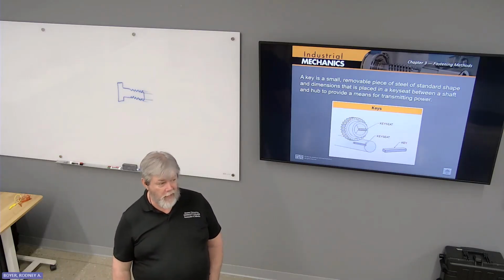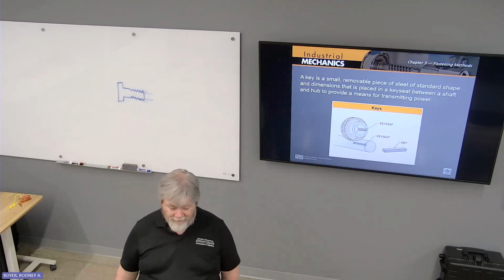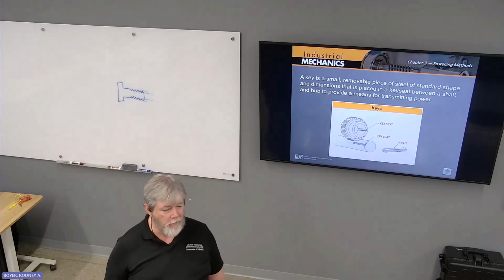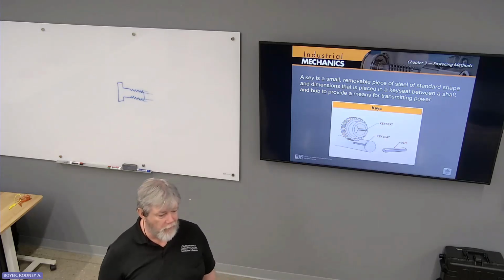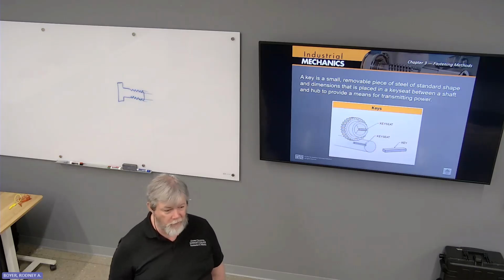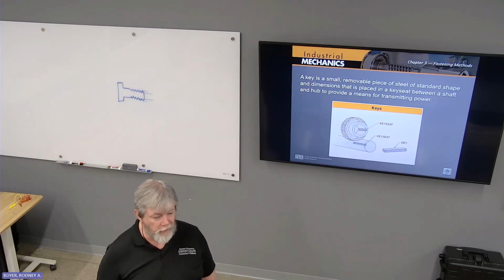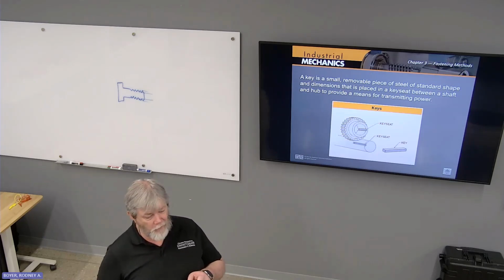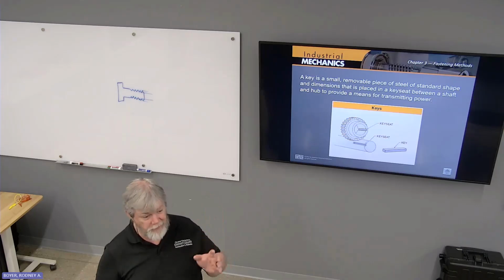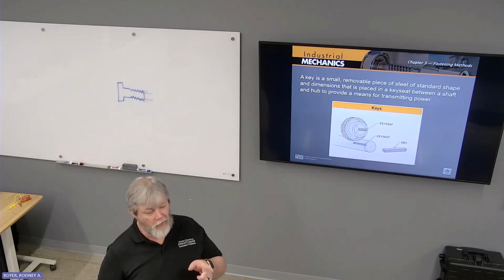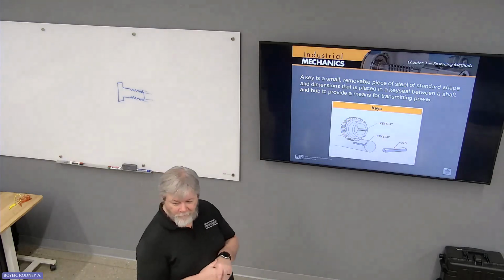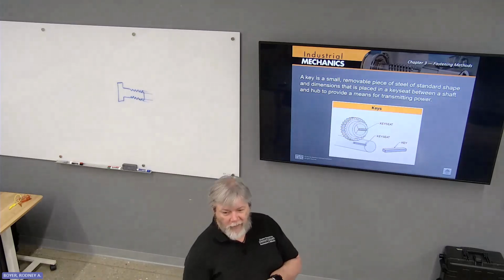Depending upon what material it's made out of, it can be designed to fail, like on old Briggs and Stratton engines, the shear key on the flywheel. If you hit a tree stump or whatever, it would shear the key, which is pretty ingenious. It would withstand a certain amount of force, and after that, it just fails. But do you know why it stops the engine? Because the ignition is attached to the flywheel, or operates off the flywheel, the ignition system does. Okay, so how does it stop the engine? By stopping the spark.